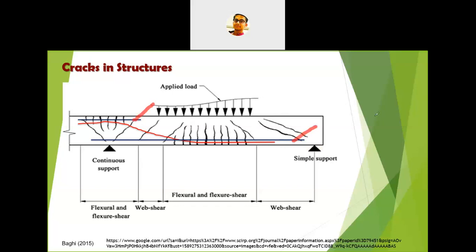So it is quite important to maintain the structures and to protect the structures from these different types of cracks, because not only will the agents ingress the concrete system through the pores the concrete has. The main reason for the ingress of deleterious agents is cracks. The easy way to initiate corrosion is through cracks, because through these cracks different types of agents are entering the concrete surface. So we'll see some examples.